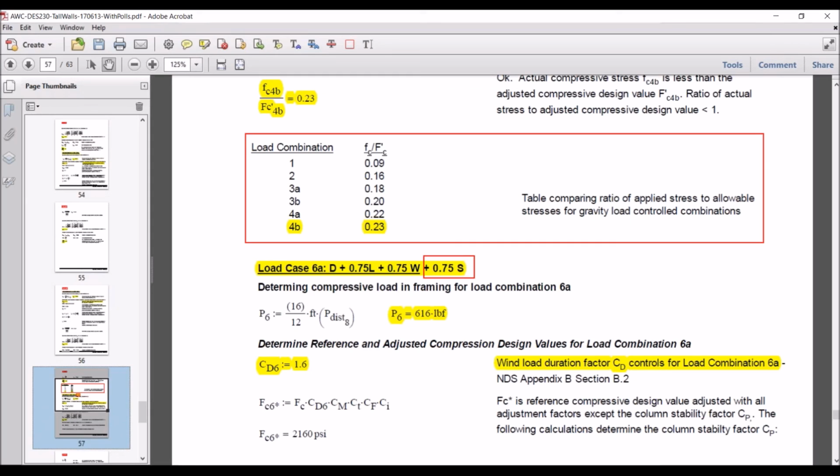Right, and anything about the adhesives that you want to add? For the finger jointed studs, if you are in a wall that requires a fire resistance rating, then you'll need to use a stud that has what's called an HRA, heat resistant adhesive, used for the finger joint. So fire rated assemblies would require an HRA adhesive or an HRA designation on the stud. Yep, and we have an FAQ on our website too, if anybody wants to go and Google it.